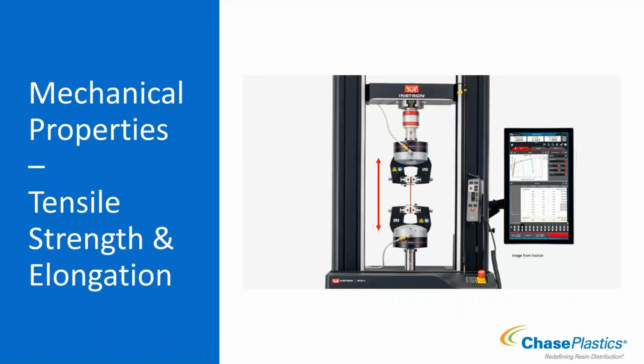Okay, so now the test and what that looks like. You can see a reddish part in here. What's going to happen is the machine's going to pull it in the opposite direction while this stays stable. And so the tensile strength is going to be how much load it can withstand as it pulls apart. And then the elongation is going to be how far it stretches before it breaks or before it yields.